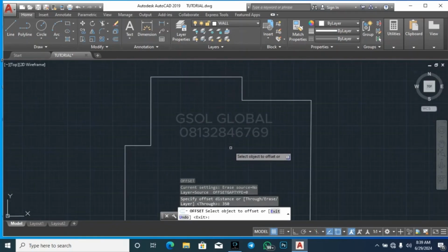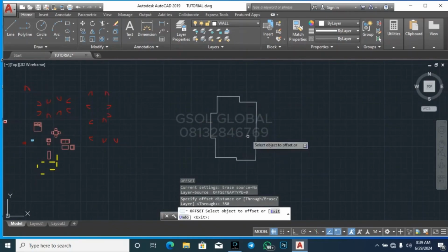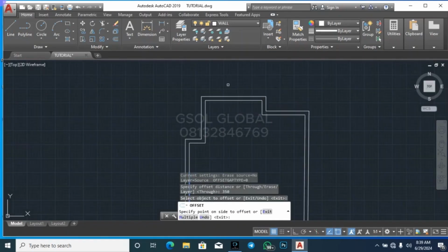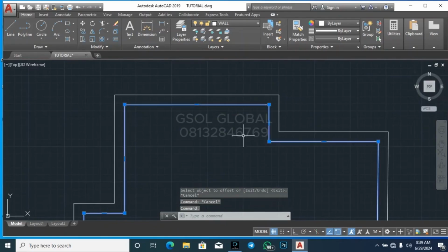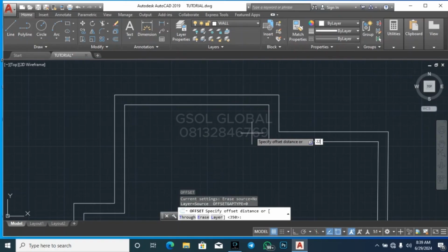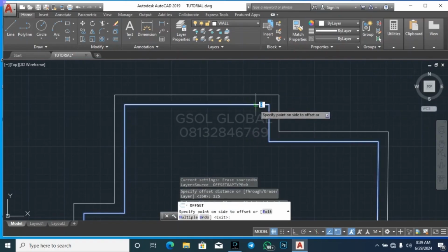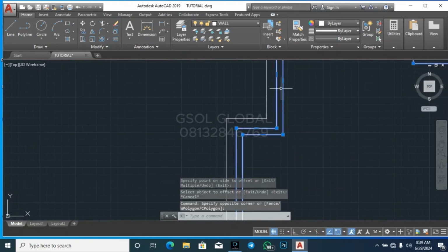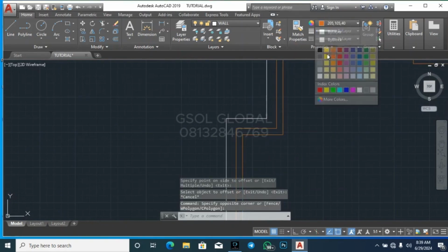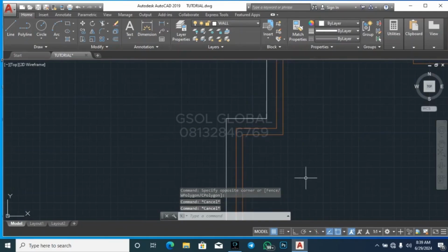from this we have 350. All right, so this is where our block work is starting from, so we'll indicate it. Offset of what? 225 for block work, so indicated. So it is right. So these are our block work, so I'm going to change this to a different color entirely. Yeah, so okay, let's make an offset first before we change to a different color.